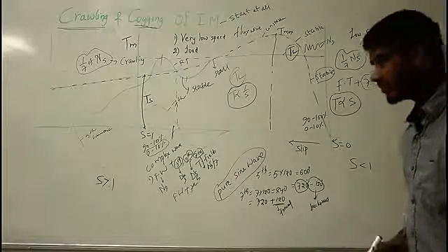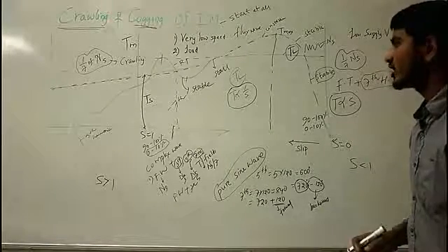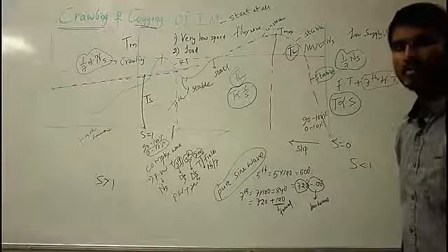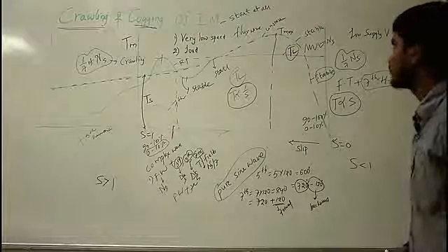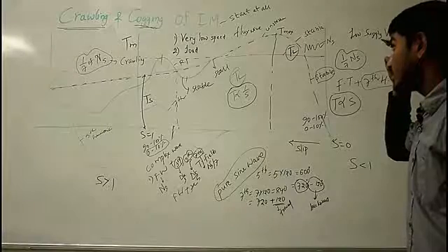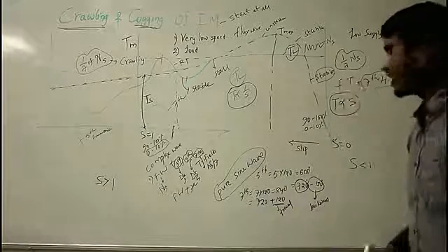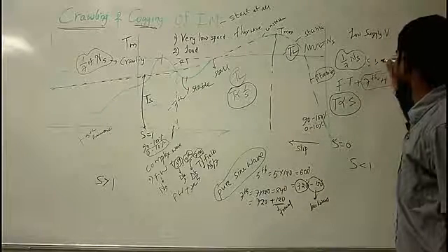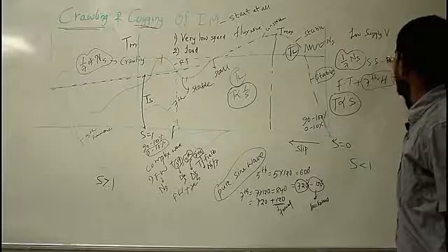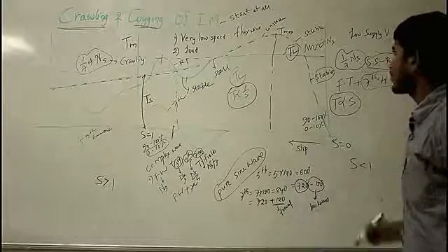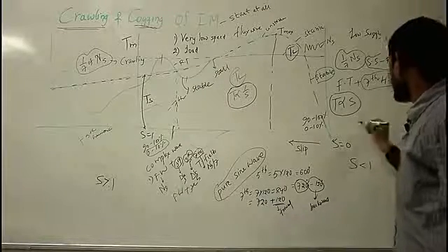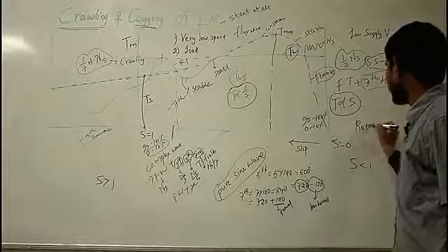But the main reason for the starting problem of your induction motor is cogging, where the slots of the rotor get locked up with the slots of the stator. That is, the stator slots get locked with the rotor slots, and your motor refuses to start at all. That means the rotor remains fixed.